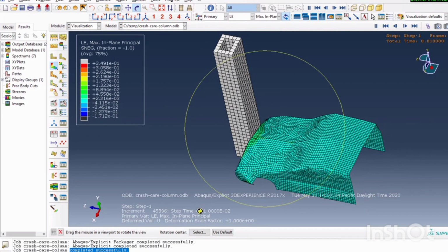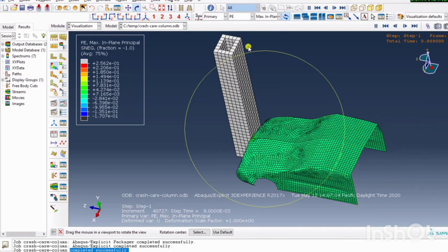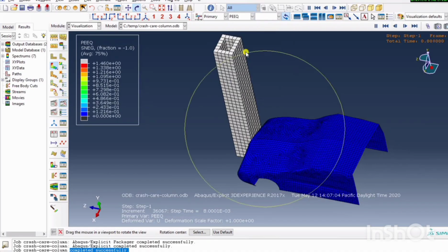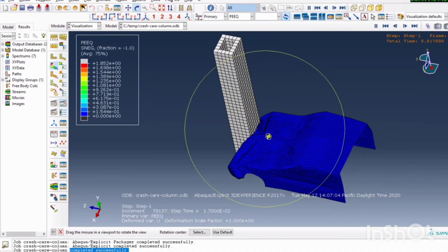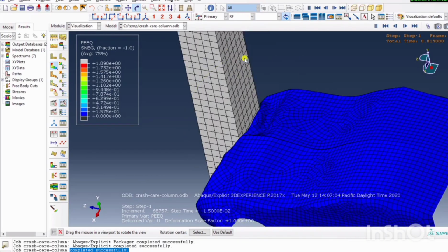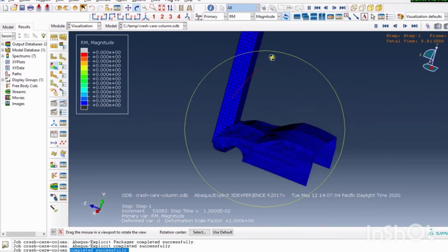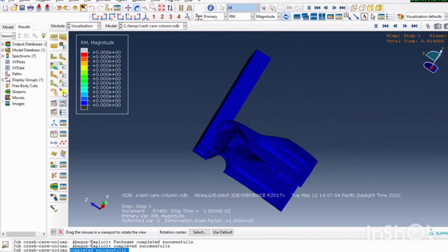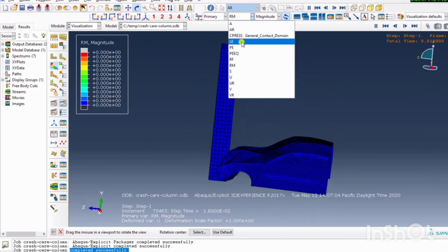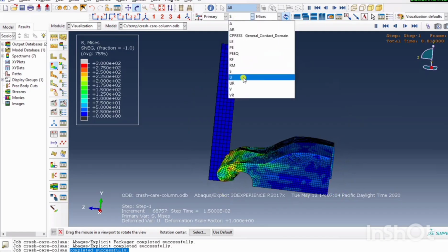Stress and strain contours highlight critical regions where failure may initiate. These insights are used for reinforcement of structural components or redesigning geometry for improved crashworthiness. Crashworthiness simulation, as demonstrated here, is widely used in automotive engineering to evaluate structural integrity and occupant safety. Abaqus enables accurate prediction of deformation, failure modes, and energy dissipation under extreme loading conditions, making it a tool widely used in modern vehicle development.